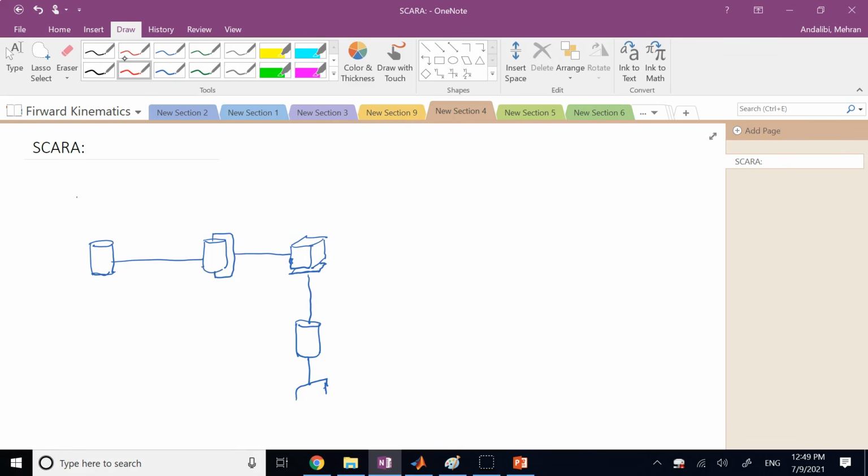Okay, step number 1, determine the z-axis, the axis of actuation. What are they? Well, these 3 rotary joints, they're all z-axes. Their z-axes are all in the plane, upward or downward. So I can say, for example, I can set this one up to be my z naught, and this one I can say is z1. Then this one goes up and down, so I can select this z to be either up or down. Now, most of the time it goes down then up, but it's up to me how I would select the positive or negative direction of z2. It has to be vertical, but which direction is positive is absolutely up to me. So here, let's say, for example, I choose this to be downward.